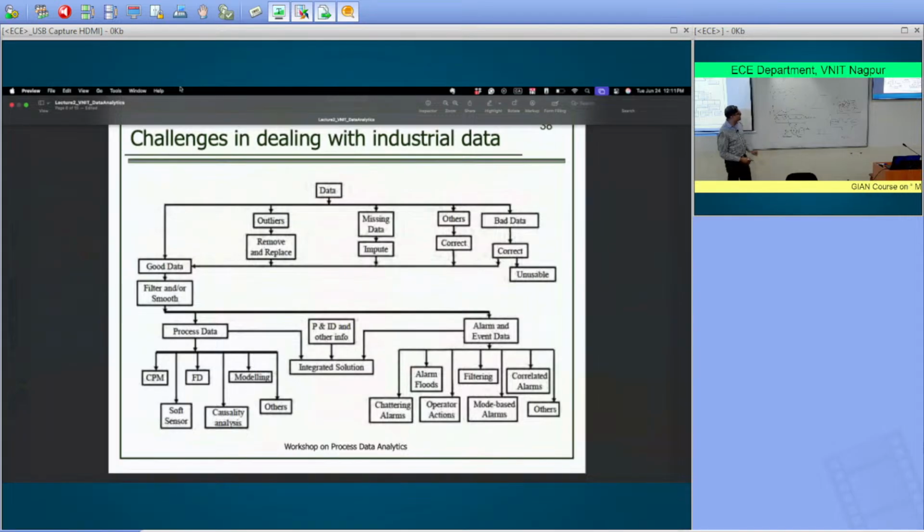There is information about that noise in the known measurements that you have. You've measured this several times in the past. Therefore, information about this noise must be embedded in those measurements. So you can use that information to come up with an estimate of this y bar t star, a better estimate than the measurement. And that is what is called filtered y. This is the filtered measurement. So you can improve it.